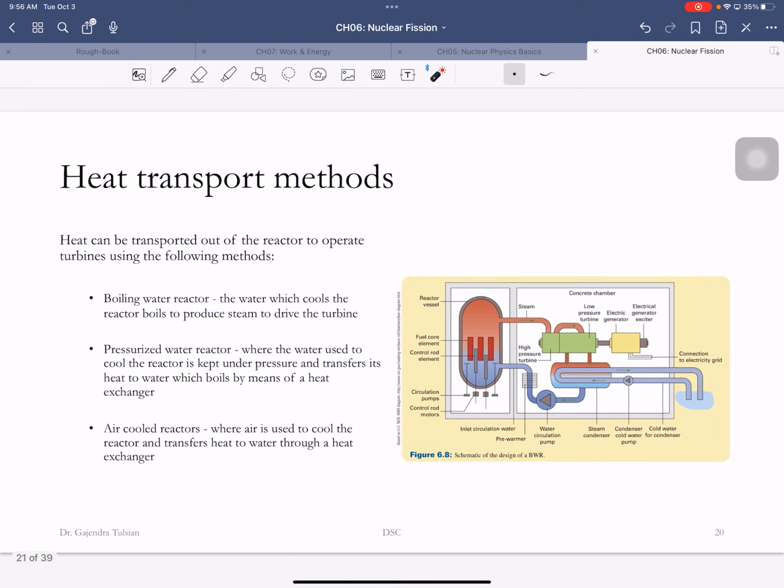So we'll talk about how to shut down a nuclear reactor. Here's water that is cooling this, removing the heat from here, and steam is coming. These control rods, if you put the control rods in, you can shut down the reactor. Now, if you shut down the reactor, those fragments are still producing heat. So you still have to constantly remove the heat. So you can't shut down these pumps. And in all accidents, these pumps have to work 24/7, 365.